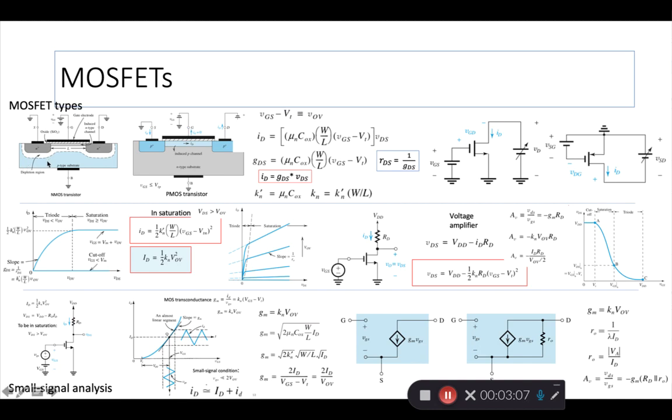And you have the MOSFET in both types. That means the N-type and the P-type, right? The P-type MOSFET is called PMOS, the N-type MOSFET is called NMOS, and there are 2 sets of voltages that need to be applied, one to the gate circuit, so the gate to source. The source is shown grounded generally, and the drain has another voltage applied to it. And so with those 2 voltages, you get the necessary amplification or switching action on the transistors, right? Of course, for PMOS, the voltages are reversed.